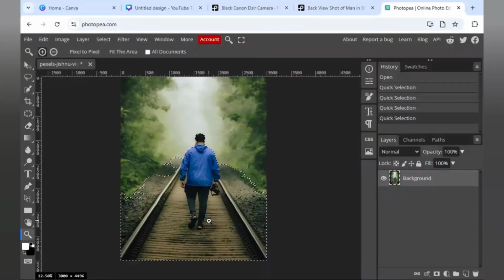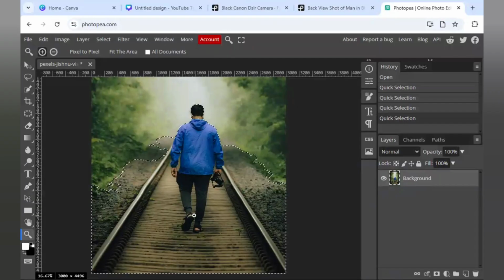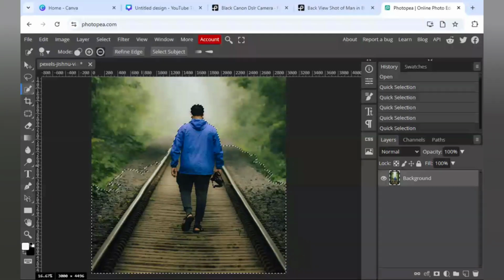Okay, now zoom it so that I can select only the Rails part. Click on W so that the selection is again available, quick selection part. Now click on Alt to select the negative icon here. As you can see, without Alt, it is selecting the plus icon, and with this, we can select the negative icon so that we can subtract the selection.